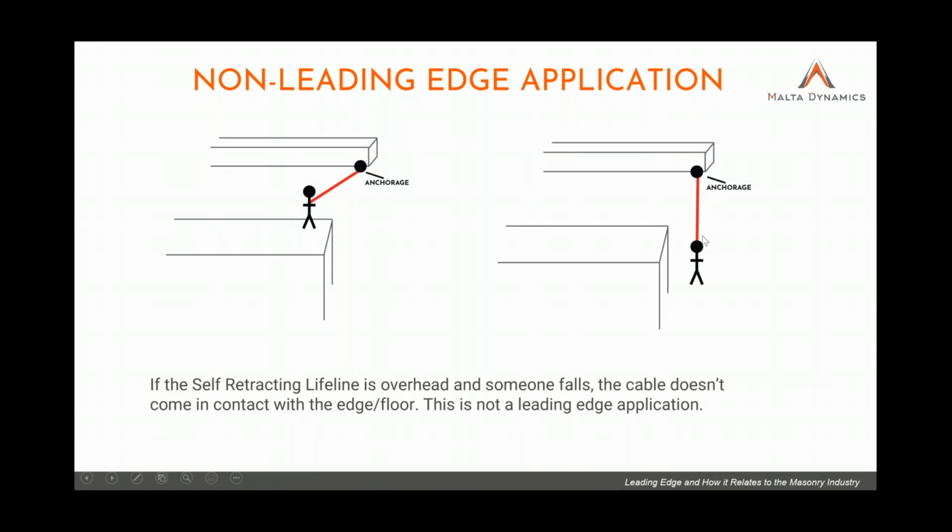All right, so if the self-retracting lifeline is overhead and someone falls and the cable doesn't come into contact with an edge or a floor or anything, then you are not in a leading edge application.